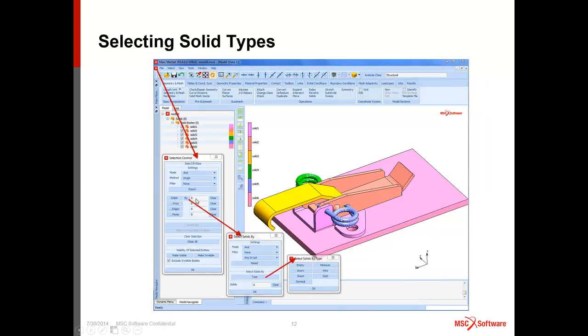Other commands that can be used are the select control. This is very useful, in that you can basically select a particular solid. You can select it by a particular thing, or by type. And if you had imported everything, you might have seen all of a sudden some loose wires or 1D items, and one could easily select those wires and eliminate them. Or you might get extremely small surfaces or extremely small solids that the CAD system gave, and you can select those minimum geometries and then eliminate them as well. Or, of course, you could have filtered them out right from the start.